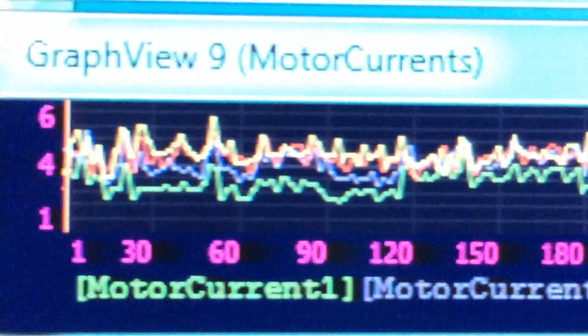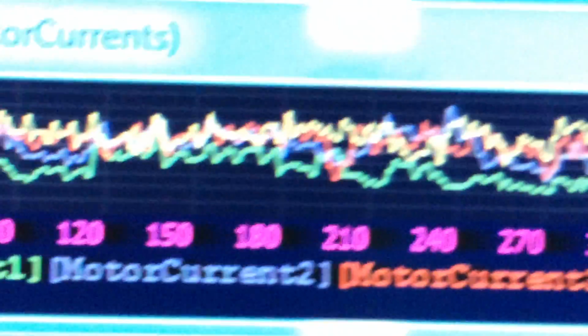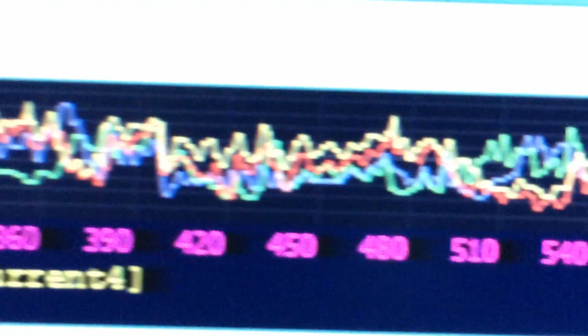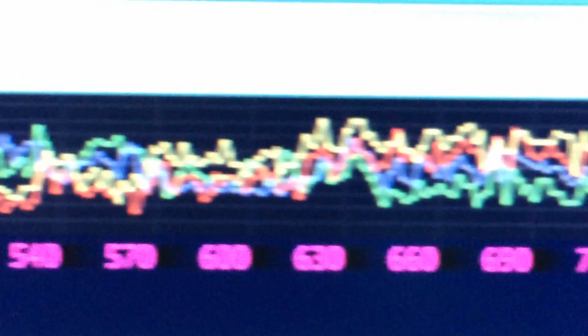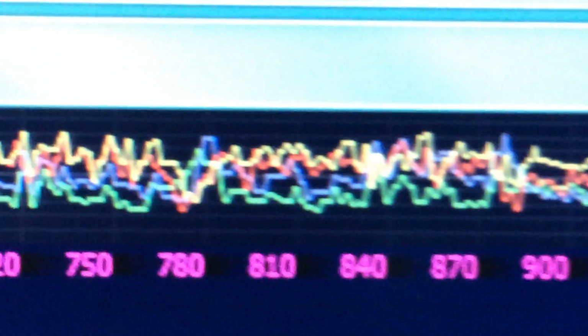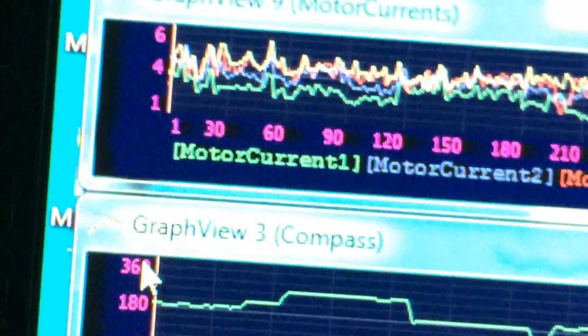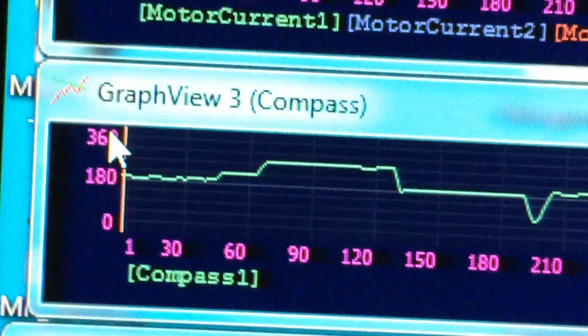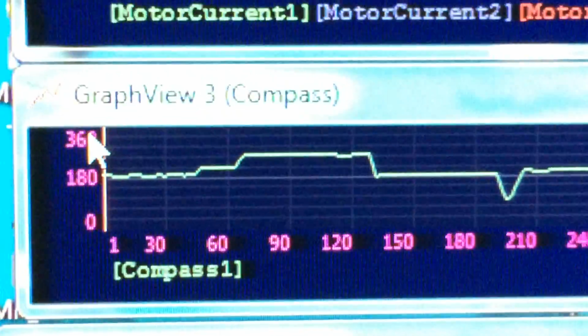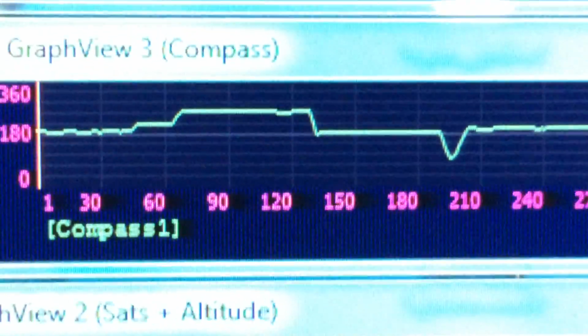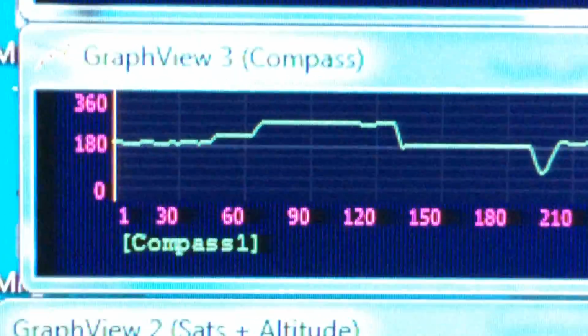The next thing is the individual motor currents, and they should all be about the same. If we see anything unusual here, we probably have a shorted turn in one of the motors. Something's drawing too much current, or one of the motors is not even on and just drops to zero. The hexacopter can fly with a bad motor, since there's 5 more to maintain stability.